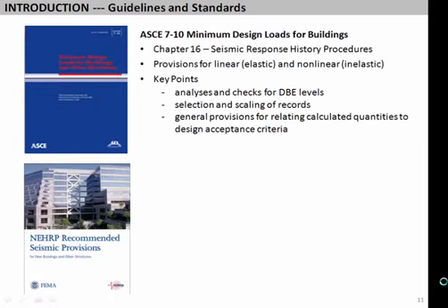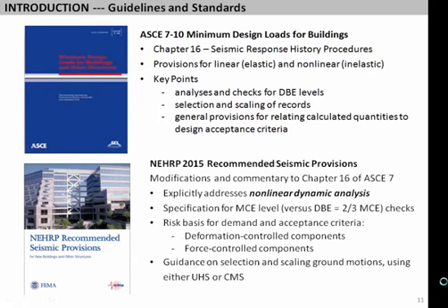And correspondingly, if you look in practice, a lot of this builds on the tall building documents and relates to ASCE 7, the loading criteria. And as Marshall described, ASCE 7 is really where we go to define ground motions and the hazards and so forth. ASCE 7 really didn't give much guidance on how to do a dynamic or nonlinear dynamic analysis, but that will be changing with the next edition, and you could get a glimpse of what's coming in NEHRP 2015. Marshall talked some about it, but it has a new draft Chapter 16 for ASCE 7 that gives more guidance on nonlinear analysis, and in fact that embraces and was modeled after a lot of the ideas developed through the tall building initiatives.